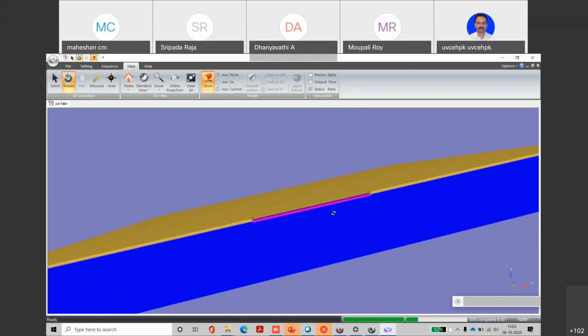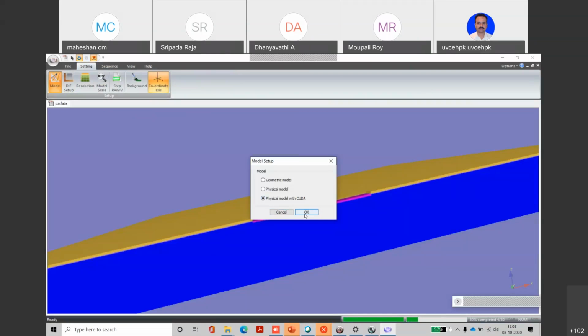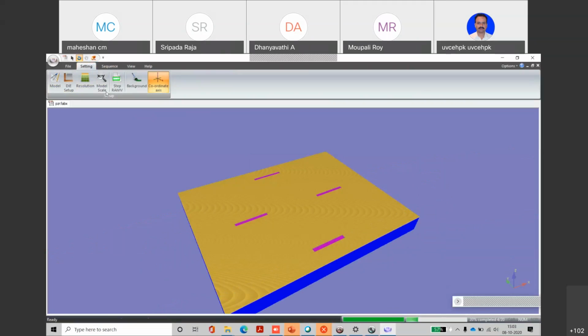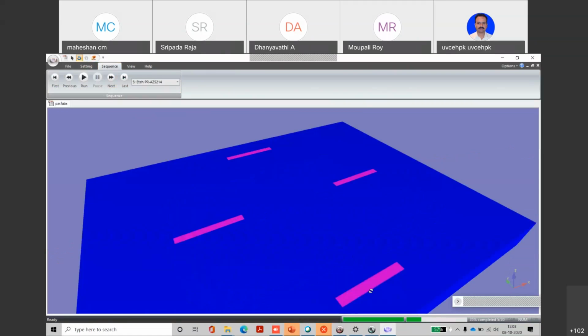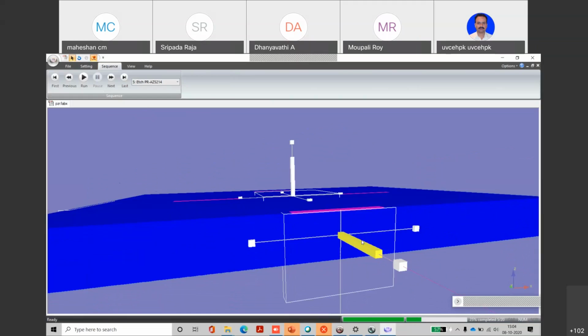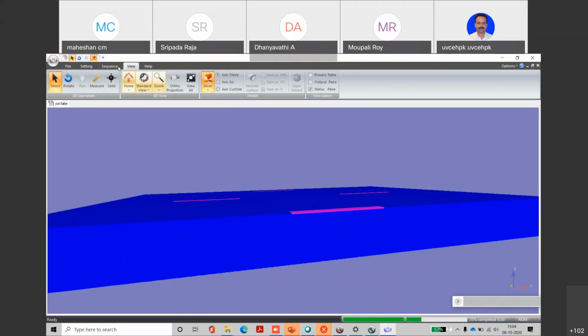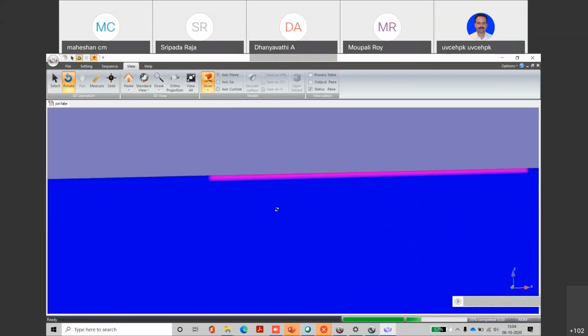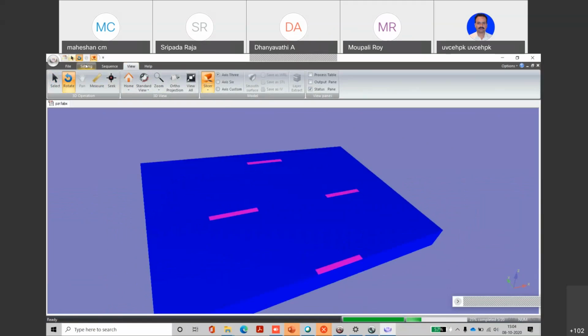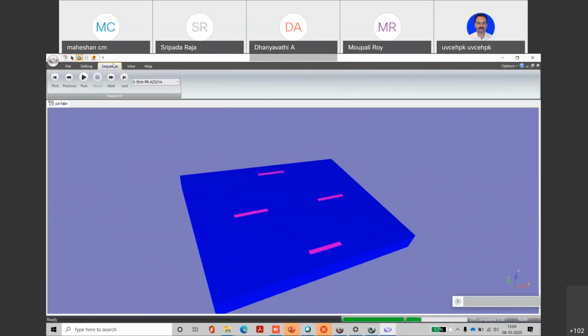So here we get this. I'll model the boron implant. So now you can see it is not on the surface, it is not on the geometry, it is inside the layer, embedded. So this is what the doping is all about. It is injecting the impurity, that's what we know.